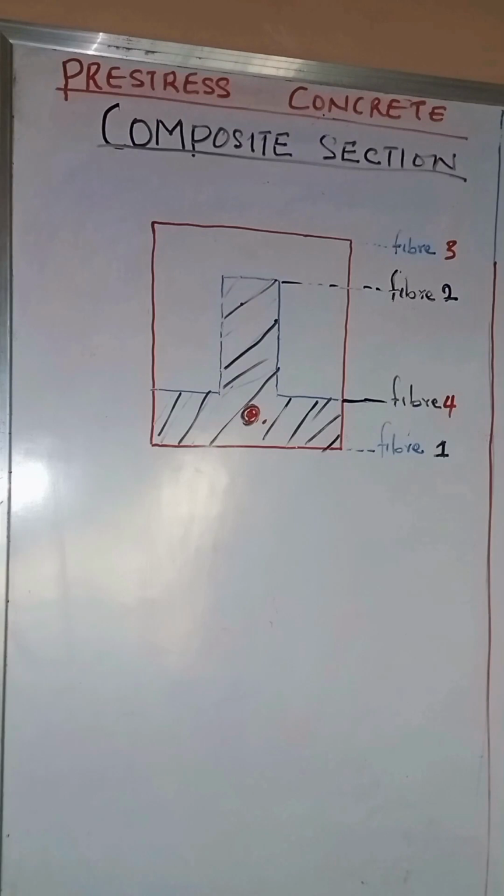So in a case where the system is not propped, we know that this is very common in most construction processes. There is the cost of propping and the inconveniences in propping. Many construction engineers are always trying to avoid that, most especially in areas where you have high traffic and you don't want any kind of obstruction to the flow of traffic.